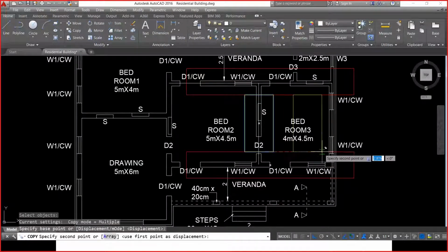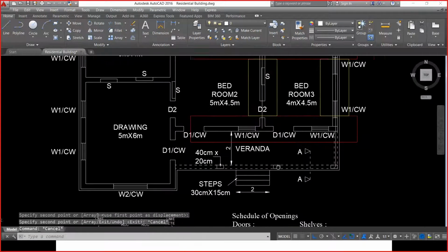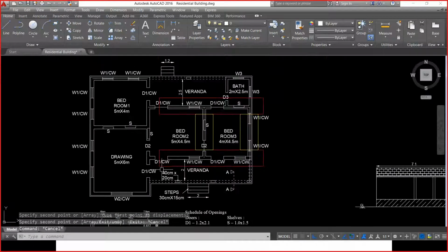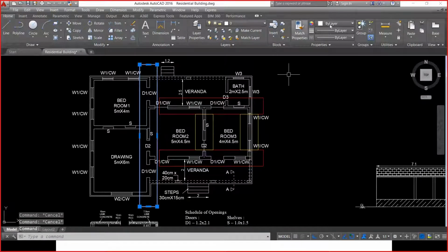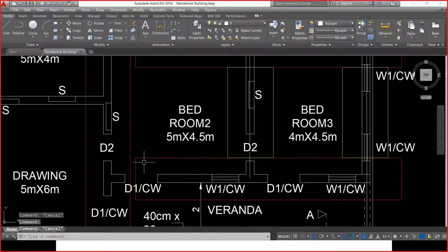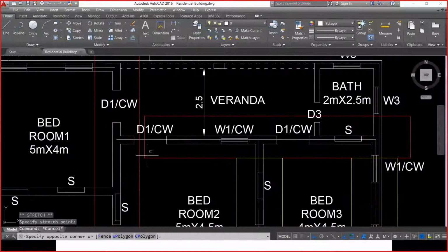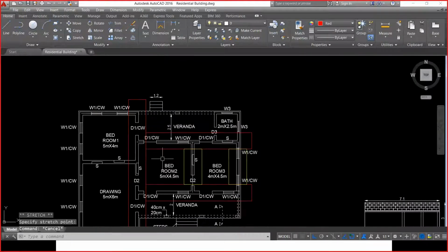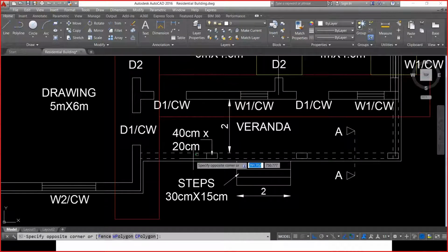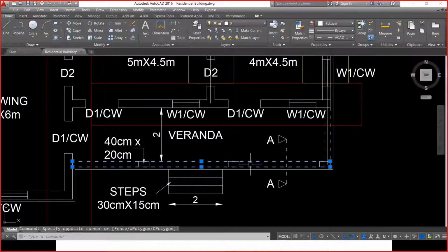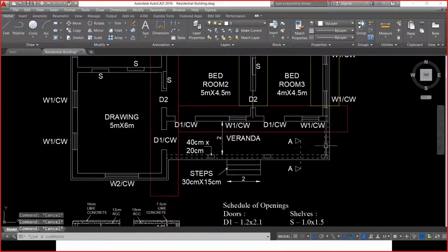Let me just copy paste it. When I look at the front veranda, this area is also done. I'm going to mark a rectangle for our reference. We have laid the PCC and done the excavation and laid the lime concrete. The next part, when we consider the front veranda, I have to go on with the calculations for the long wall, partition wall, and the short wall. Of course, it is also a partition wall of thickness 20 centimeter.